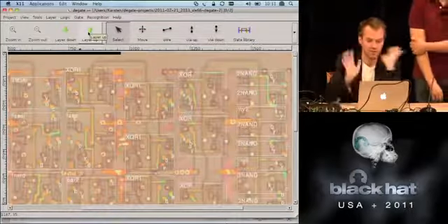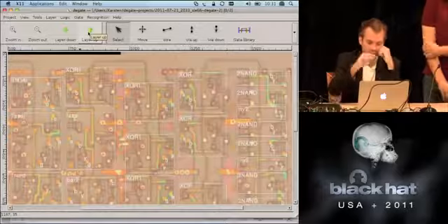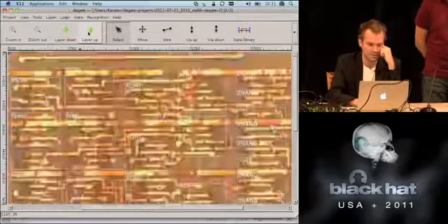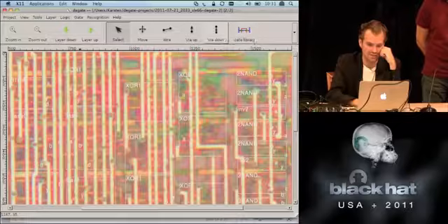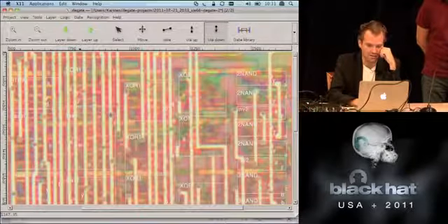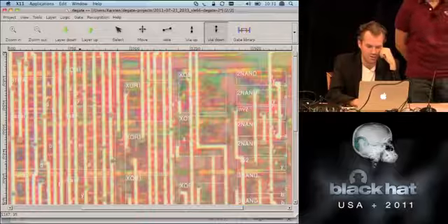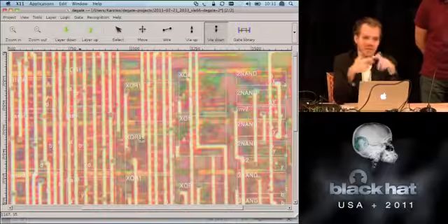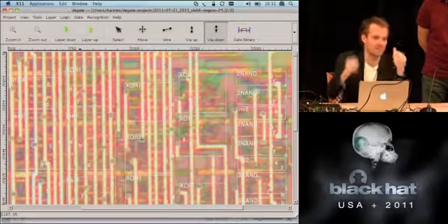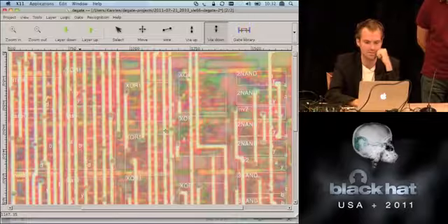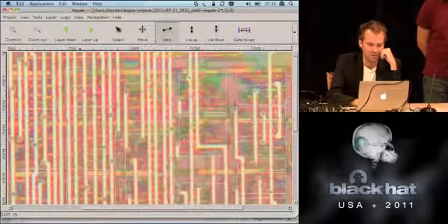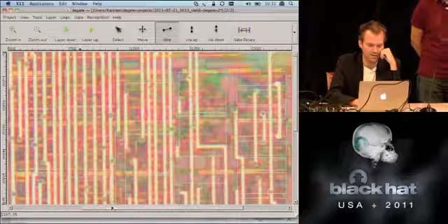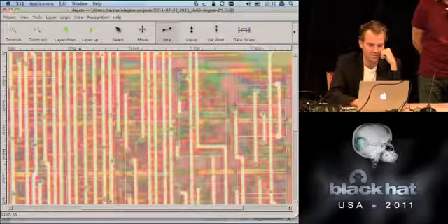Yeah, and now it's really just dumb work of finding how they're connected to each other, right? So you start at the highest level and you say, okay, these are all these little dots that are going downwards apparently, right? So you mark them all, and the program will tell you when you missed something because everything has to be connected to something else. There are no loose ends in the chip, right? So you start somehow, and you start connecting. You say, okay, here seems to be a wire that's running down here. Oops. And there's another wire that's coming down here.